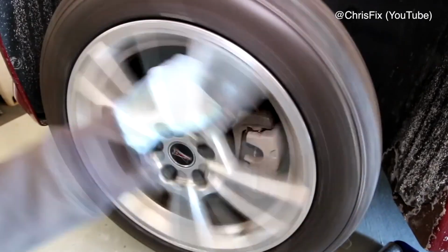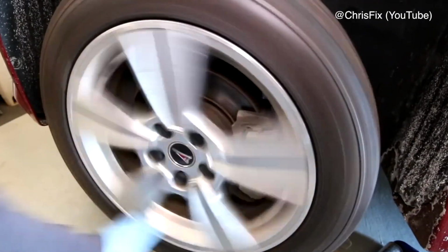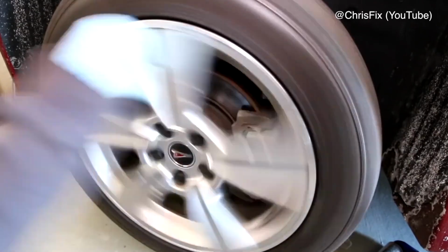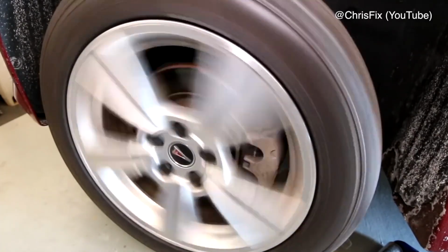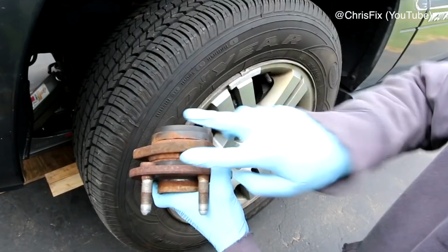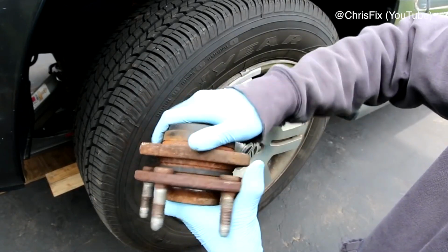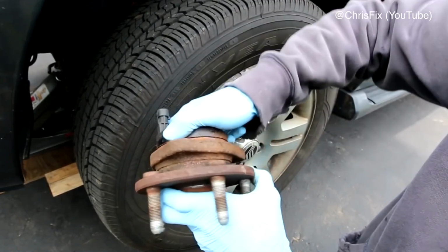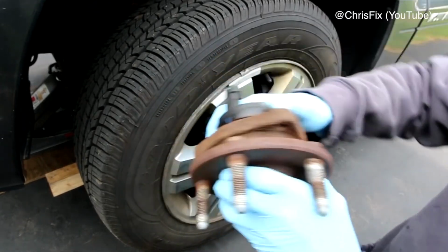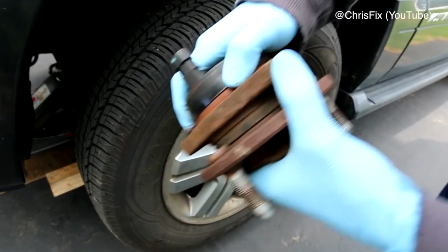I'm pretty sure you can hear it, so that's what that is. It's pretty freaking loud. I'm trying to separate the bearing like if we're shaking the tire, but there's no movement here, it's solid. But it feels gritty, it doesn't feel smooth. And let me put this up to the mic so you can hear it.